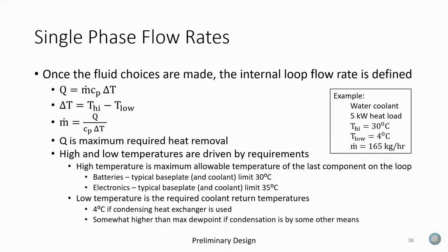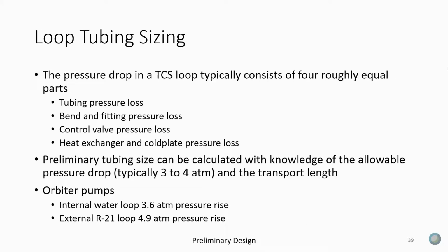So it's never a clean thing about what is better and what is worse. But if they give you this temperature, you really want to use your higher temperature simply because that lets your radiators run hotter, right? I could say I want to, even though I'm not condensing, I'm going to send 4C liquid to my system because I want to take that full 26 degrees of temperature change through the system. But you really want to use your highest temperature simply because this raises your radiator temperature, increases their performance.